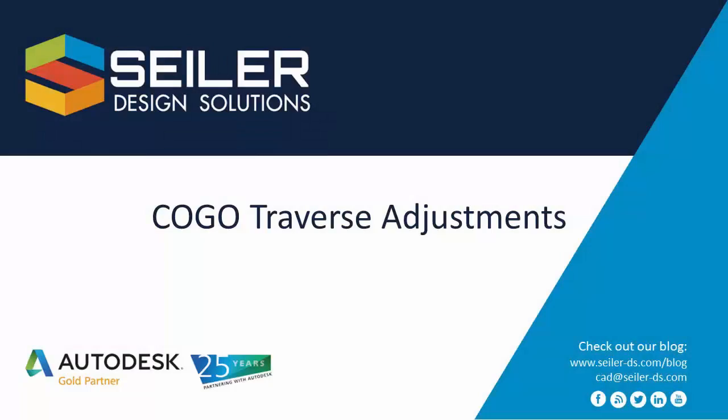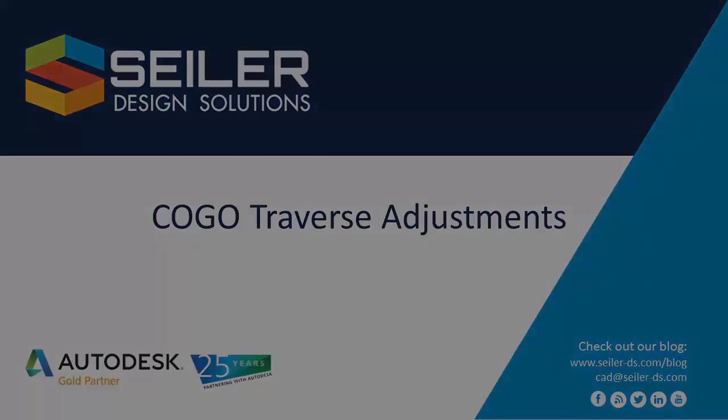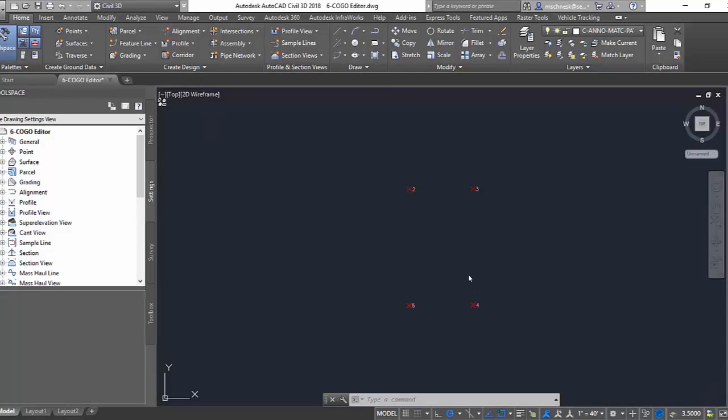In this video, COGO Traverse Adjustments. New in Civil 3D 2018 is the Traverse COGO Point Editor and Adjustment. Here I have a drawing where I have some COGO points that were brought in from points shot in the field. It runs number points 1 through 5, where 5 is my closing point on 1, and you can see we have a little closing error here.